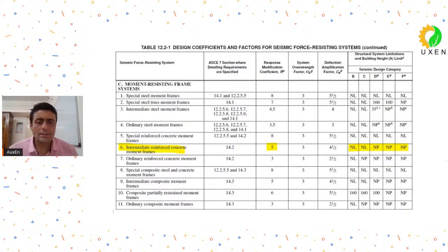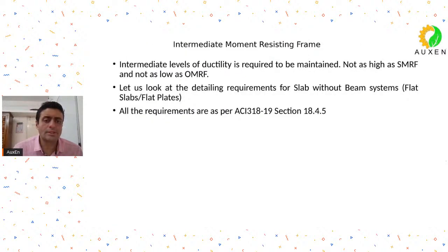Here, I must add that seismic design category C means a substantial earthquake. You could say in the Indian context, up to let's say some parts of the Deccan Plateau of India, large parts of southern India, all these will comfortably fall under seismic design category C as per the American code. So the American code does allow you the use of this system.